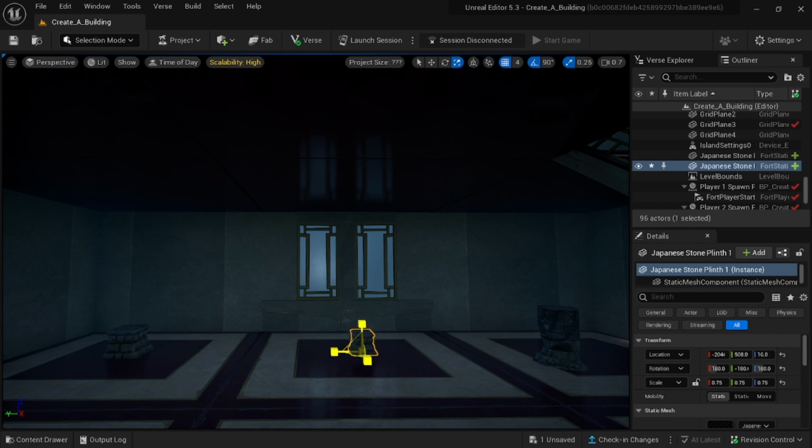orientation, and size. Note that when using Scale, you can change the scale of an object and maintain its proportions by clicking the white cube in the center of the gizmo and dragging with your mouse. If you click an individual handle on the Scale tool, you will only change your object's relative size in one dimension. For example, making it taller or wider.